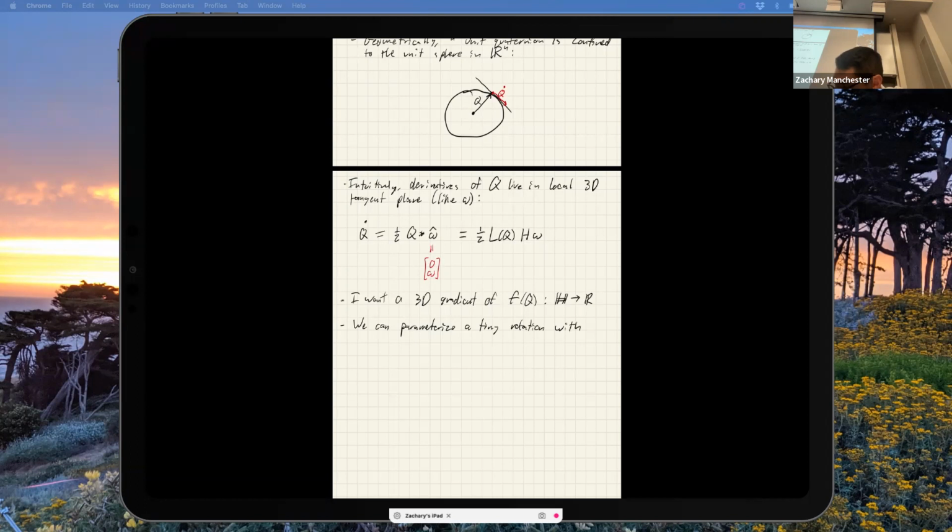With an axis angle vector. You could choose anything. You could choose Euler angles if you wanted to, any 3D representation. We're going to use axis angle vectors because, for small rotations, basically to first order in a Taylor expansion, they correspond to an omega times a delta t. So this is the closest thing you can get to integrating omega, right? They actually do correspond to omega times delta t if you're rotating about a single axis. But if you're tumbling, they don't.